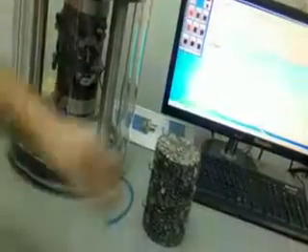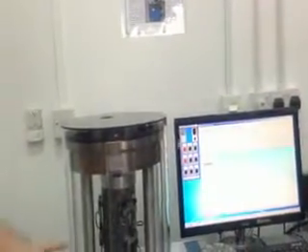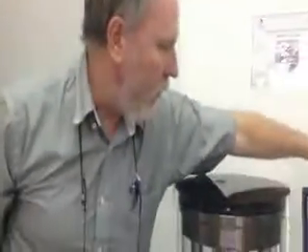So if we just put an estimated value of 2,000 MPa, 2000 megapascal, right? This sample we had in here back in April when we had the open day of the complex. We ran some tests here, and I think we got the 25 hertz was around 2,000 MPa modulus. So if we put that value in as our initial seed value,